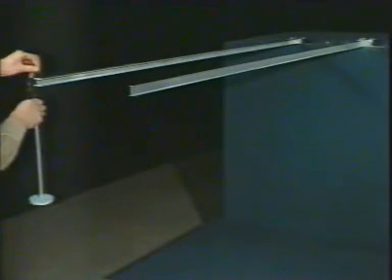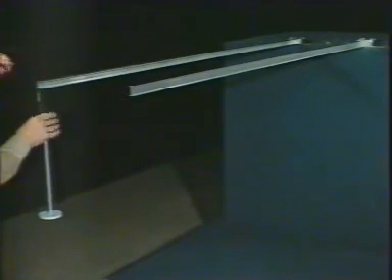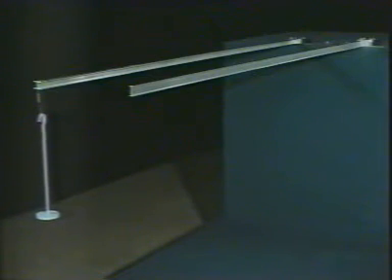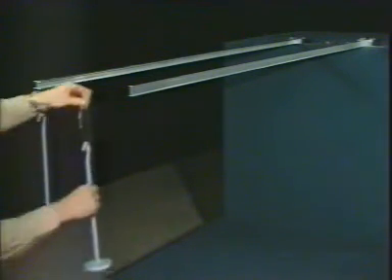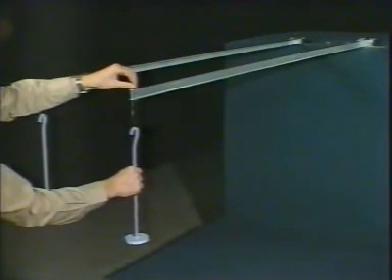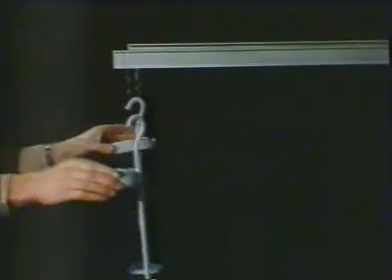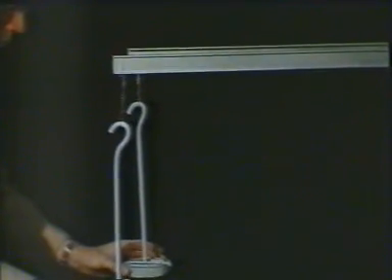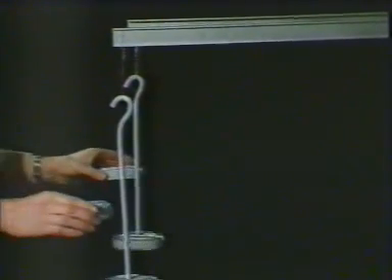Observe the response of the two cantilever beams which are of equal length and which have nearly equal major axis flexural rigidities. The one on the left has a high minor axis stiffness, whilst the one on the right has a low minor axis stiffness. Initially, as equal load is applied to each beam, their behaviours are almost identical.